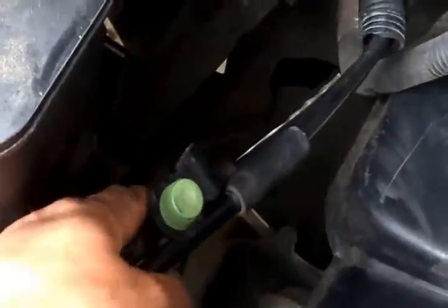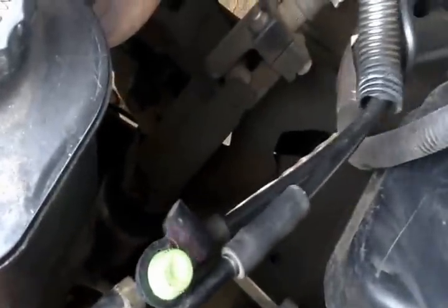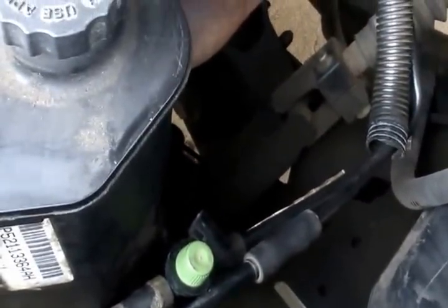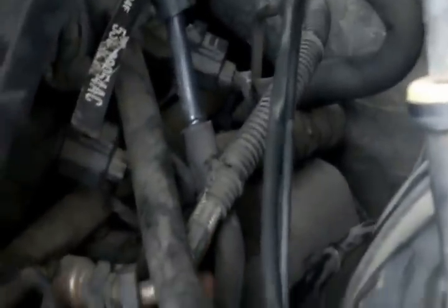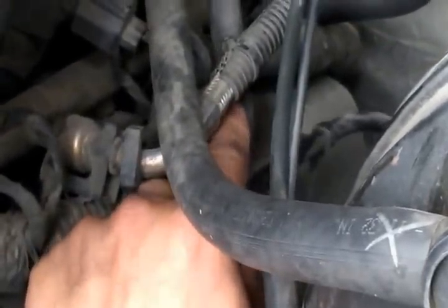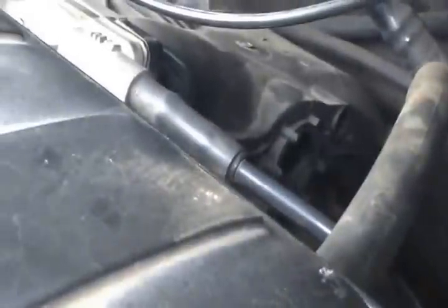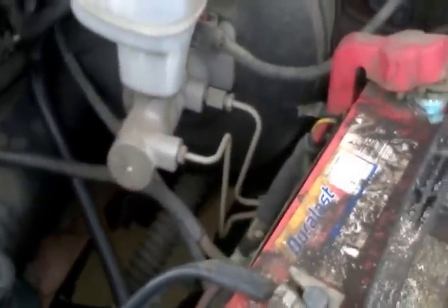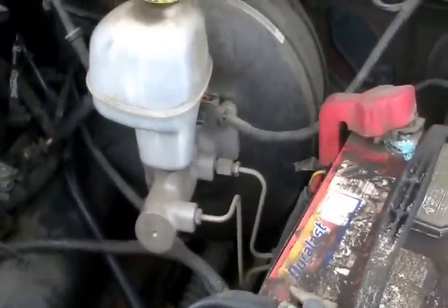So the next visual inspection will have to be at the evap canister, and also take a look at those hoses. But I also see another connection here, this L-shaped rubber hose. This one also looks good, and it runs to that throttle body port right there. It doesn't feel brittle. I don't feel any cracks. So I'll say this visual inspection here at the engine bay is pretty much good. So I'm going to take it to the evap canister, which is below the truck.